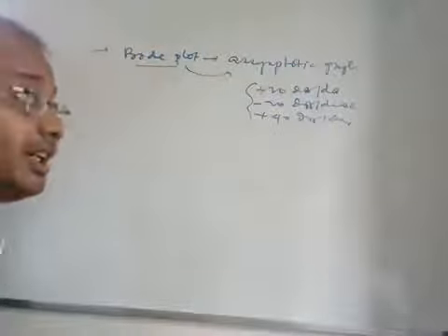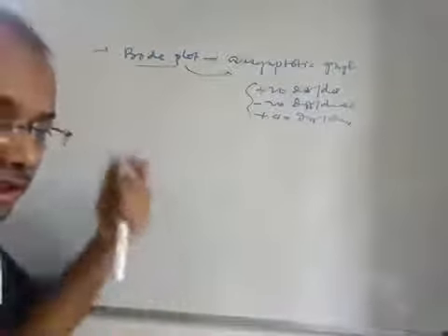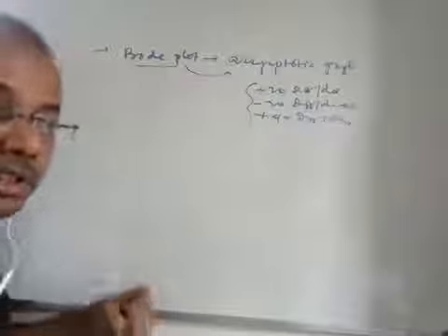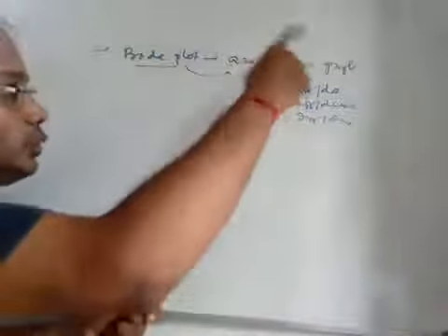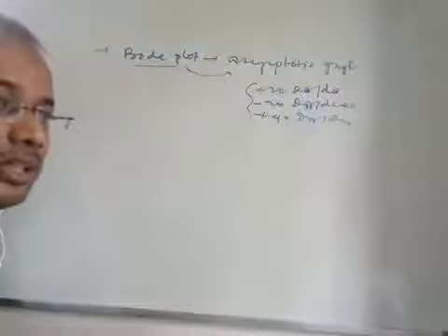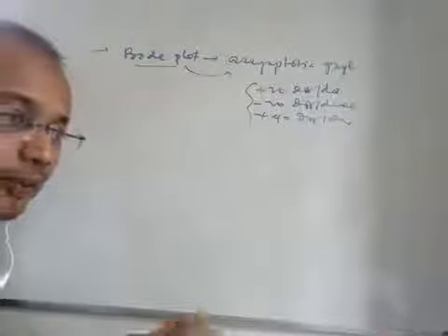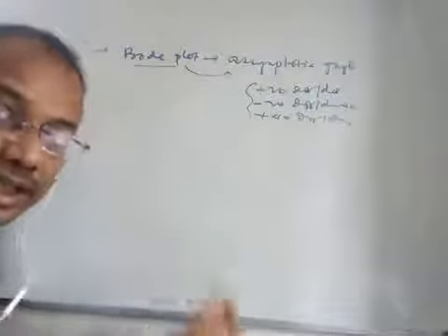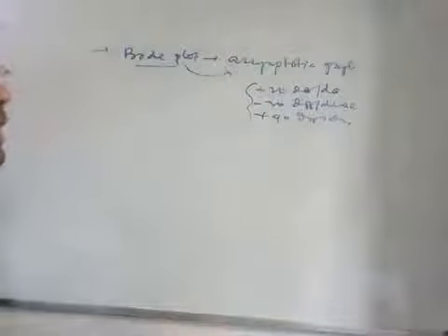Actually, if you vary the frequency, all these magnitudes may not be following straight lines. But in Bode plot, what do we do? We do the asymptotic graph. Asymptotic graph means the approximation to the straight line, that is straight line approximation of the actual graph, and that is why this is known as the asymptotic graph.